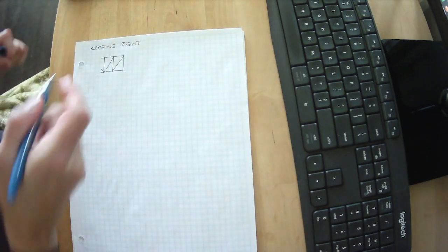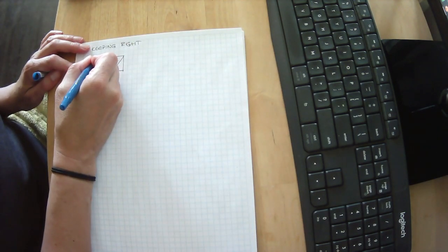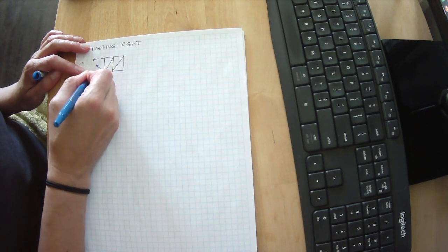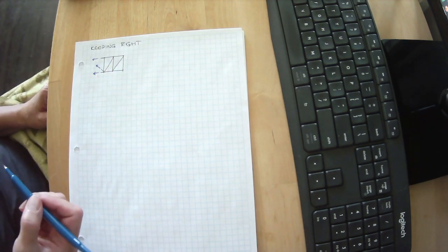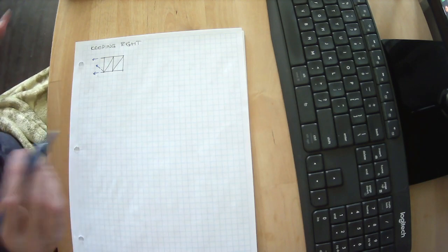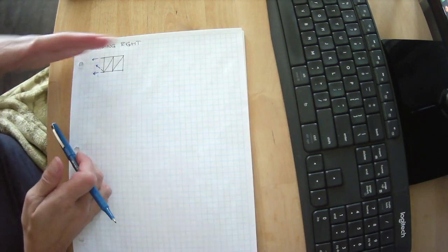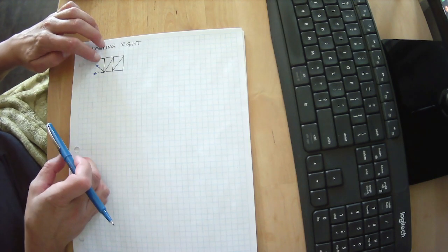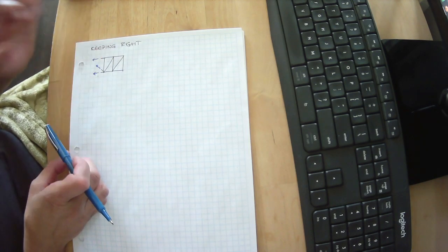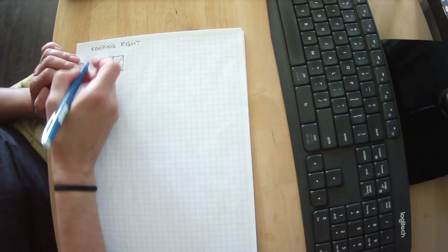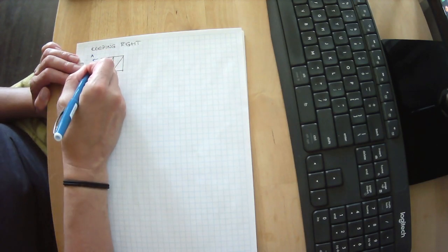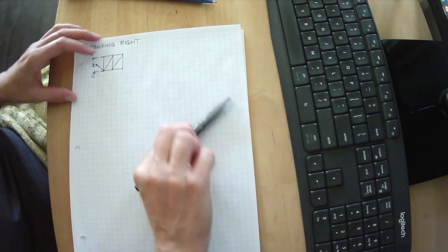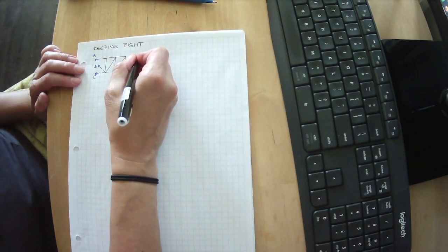Okay, we know that there must be internal loads, and again, even though we've already solved this, I am going to assume everything is in tension. Remember, the arrow pointing away from the cut means tension. The direction doesn't mean tension or compression. It's whether it's acting away or towards the cut that tells us if it's tension or compression. We're guessing that all three of them are in tension. Because we don't know, we might as well have some sort of consistent method.